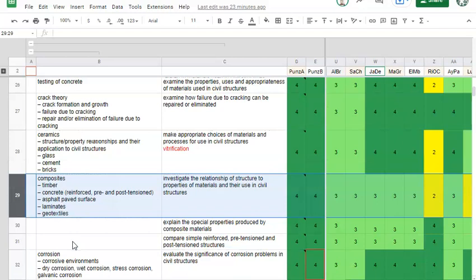Geotextiles, really important to prevent erosion. Geotextile fabrics, also really important for drainage. I went into this in a lot more detail when I recorded this previously, but I'm just going to say geotextile fabric, really important for drainage, right? If you don't have good drainage, if the foundation gets flooded, well, you can have your basement get flooded, and that's not good. I would hate it if I went to my basement tomorrow morning and found that my car had been flooded, right? And it's also not good because if you have a clay soil and you get too much water in the soil, that's not good. Not part of the HSC course, but if you don't have good drainage, everything built on top of the soil is in jeopardy.